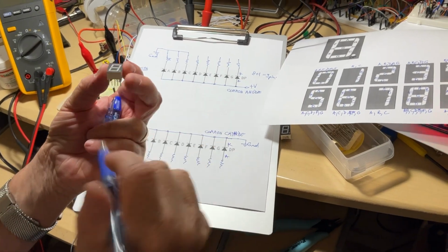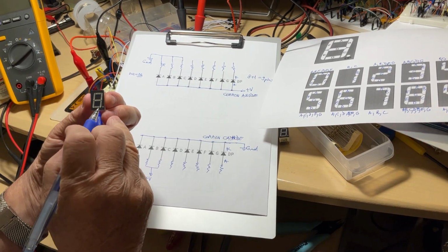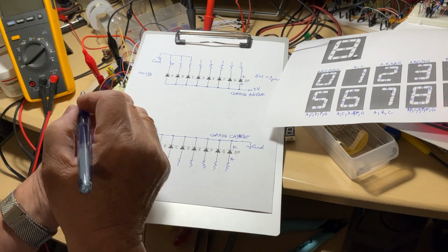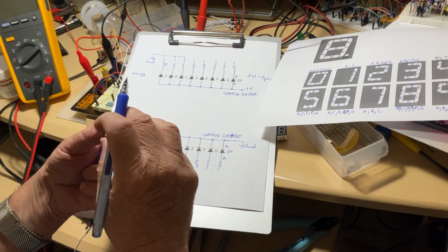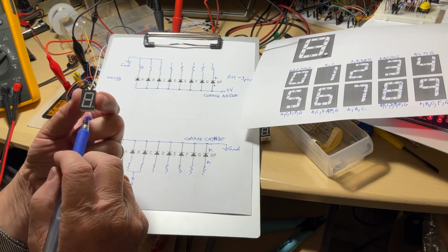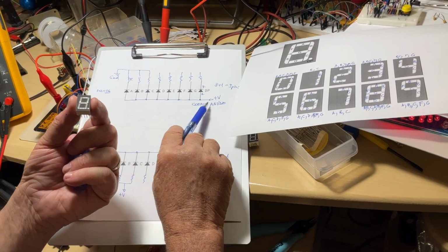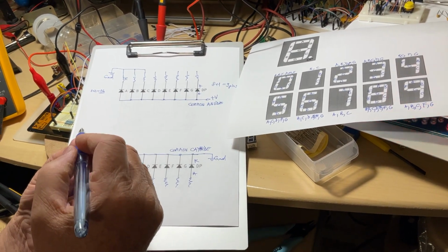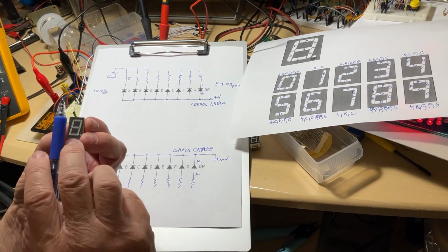It's because there are 2 rows of terminals. If you keep the digit aligned with the decimal point on the bottom right, there are 5 terminals in the bottom and 5 in the top. So for some practical reasons, for the designers to have access to the common terminal on both sides, there is one common present here in the bottom. So one of the 5 terminals in the bottom is going to be the common anode, and there is going to be a second common anode in the top. And obviously, the 2 pins are going to be related inside the package through a wire.